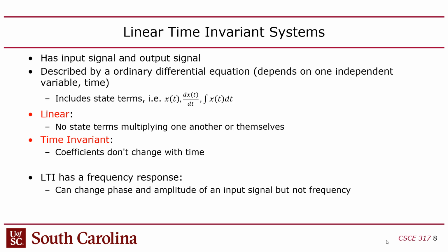Okay, so LTIs are known to have a frequency response, which is if you put a sinusoid into an LTI, and I'll talk about what that actually means to put something in, because technically an ODE doesn't have an input or an output, but we'll talk about how that's conceptualized. But if you have a system based on LTIs, and you put a sinusoidal input in, they can change the phase and the amplitude, but they don't change the frequency, right? So you can build a linear filter, where you can have it attenuate certain frequencies, get a gain on certain frequencies, and change the phase. But the output frequency will always be the same as the input frequency, right? And that's a restriction you have with designing those as LTIs.